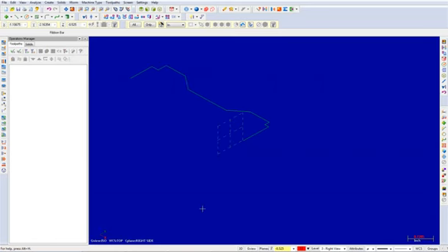Also, change the construction depth and mode to 2D as shown. Press Enter. Your part should appear as shown. From here, pick the Create Arc Circle Center Point command.